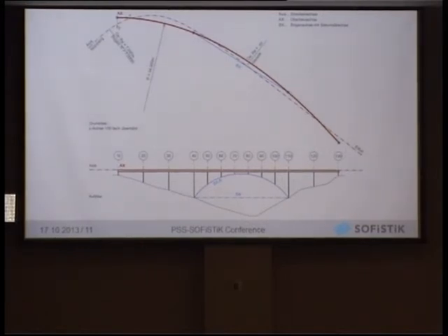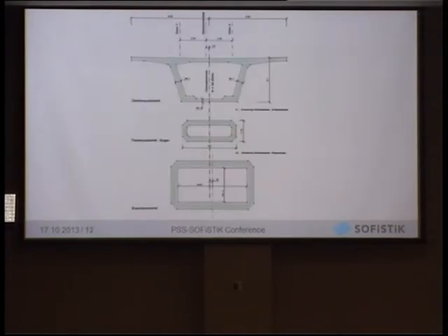Furthermore, we have to consider the eccentricity, of course, of the track towards the structural axis. And furthermore, we want to have a straight arch, right? Because the arch itself has to maintain, hopefully, normal forces and a lot of moments due to the incremental launching. So we don't want to stress it with additional curvature. That would be quite stupid. So the arch acts as a tangent somewhere in between, more or less, these elements. So this bridge is on the second glimpse geometrically quite an interesting one.